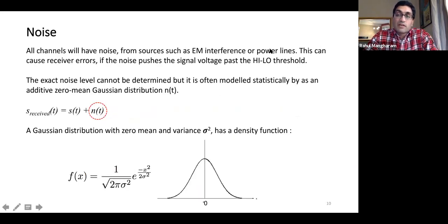And if you go to what Shannon's law says, let's start with this: when I send a bit, I basically have a probability that that bit is centered around 0 over here. So this is, say, a Gaussian distribution of sending a particular signal, and it has this kind of variance over here. That's the density function of the Gaussian distribution.